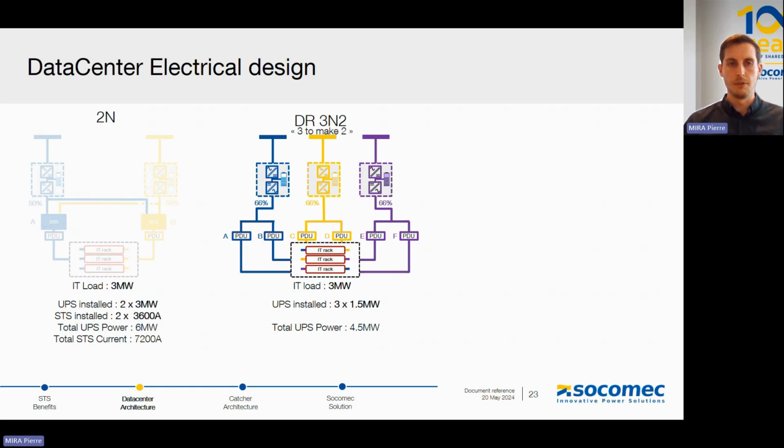It's very important to understand this in order to do the right sizing of the UPS. In a distributed redundancy architecture, if we are losing one UPS, all the other UPS will be ramping up in order to manage the power sharing to the load. So at this moment, we don't lose the load. Again, we are in a data center, so we must not lose the load.